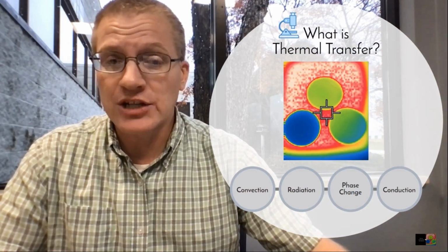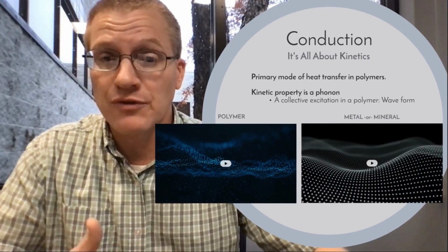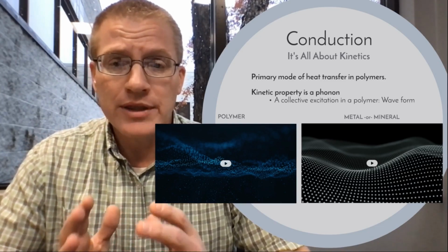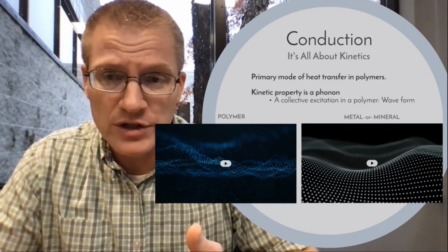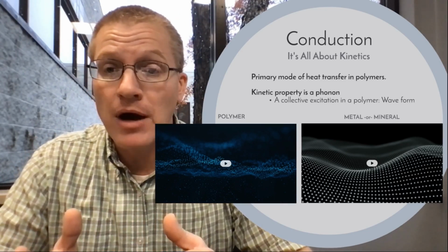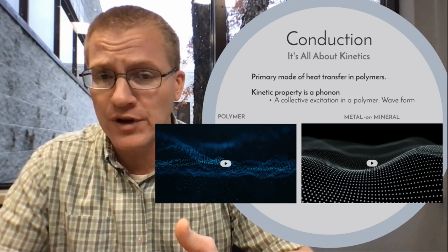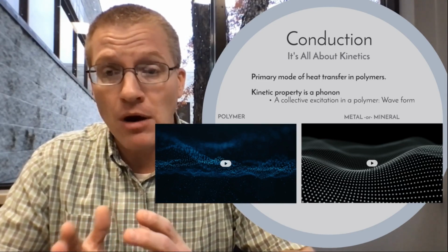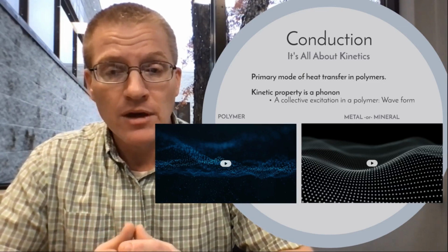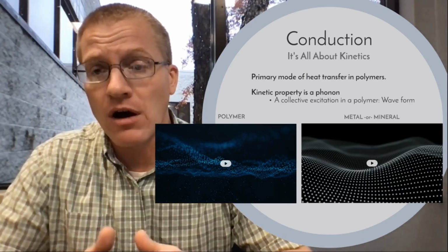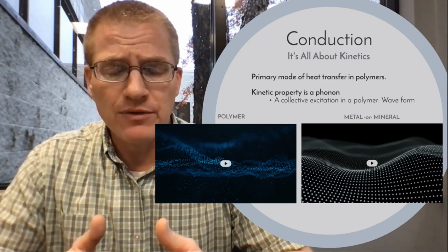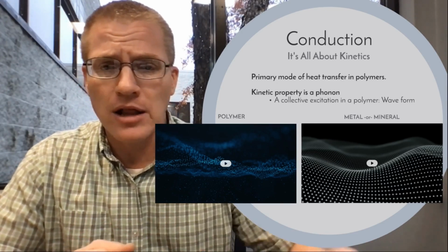The real big section is thermal conductivity, or conduction of heat. And really, conduction is all about kinetics. It's all about the contact that molecules have with one another and how those molecules are in contact with other things in a compounded system. So when we're looking at polymers, we're going to talk about fillers. Ultimately it's particle contact, all right? And that particle contact is based around what's called a phonon. A phonon is an excitation wave of the particular molecules. Think of it kind of like a sound wave. We're going to talk about this more when we get into polymers.